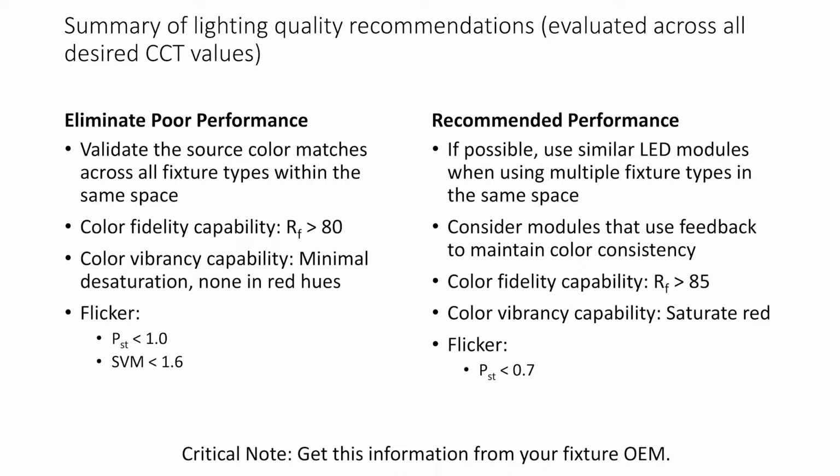What is the color fidelity? There's a new way of measuring and representing color. We're all used to CRI, the color rendering index, which is a palette of 14 colors, and it's how well those colors are visualized compared to an incandescent or a light source like the sun. It's sort of equivalent to CRI is color fidelity. If I have something better than 80, that would be good, but 80 is still pretty poor.